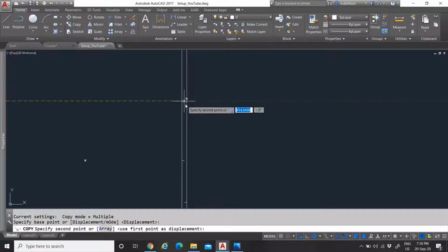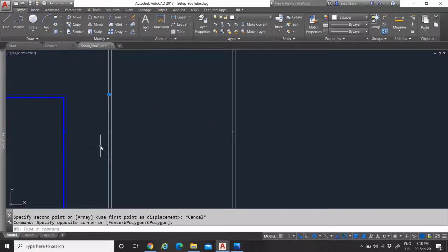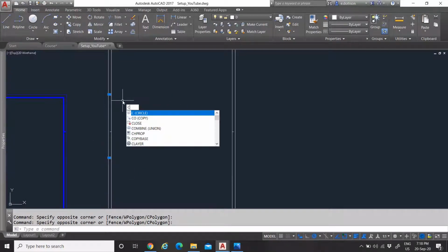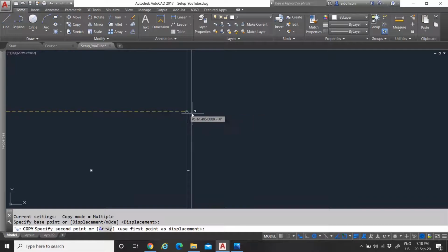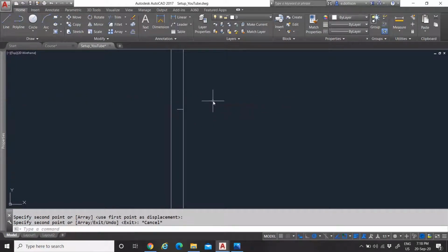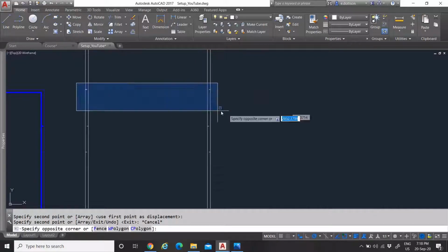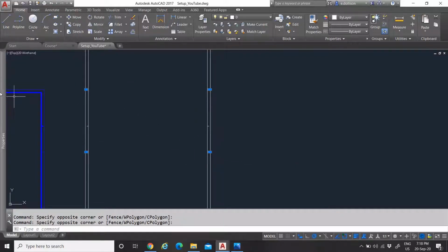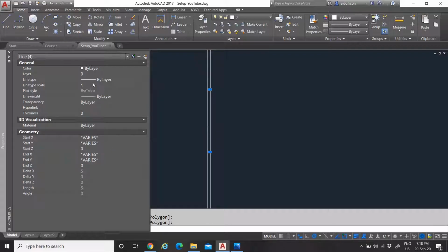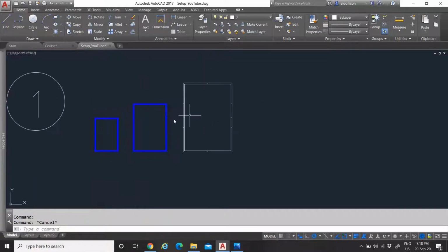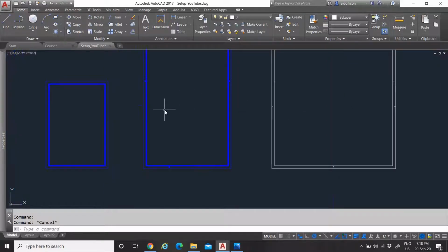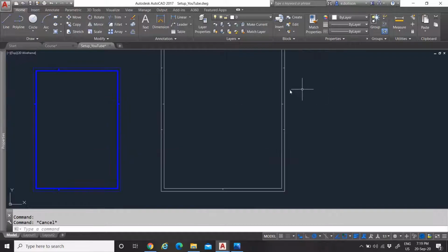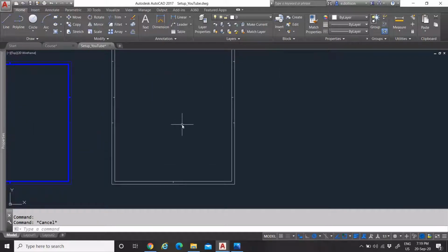Oh, no, sorry. Again, I'm so sorry, guys. Select it one more time. Type CO for copy. Select the right corner. I was right the first time. And then we're gonna bring it to our outside line. And these lines, we're gonna select all four, go in our properties, and we're gonna make this line width 0.00. As we did with this one right here, our outside lines, which our guidelines are on the outside, is for our landscape view, to fold our landscape paper.